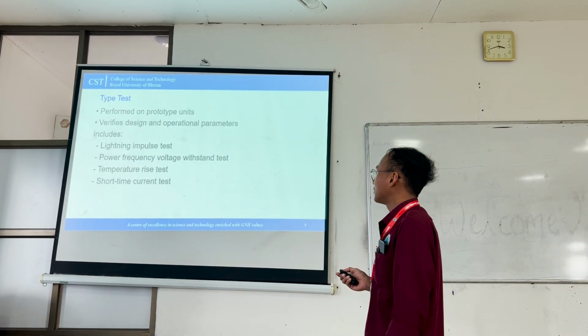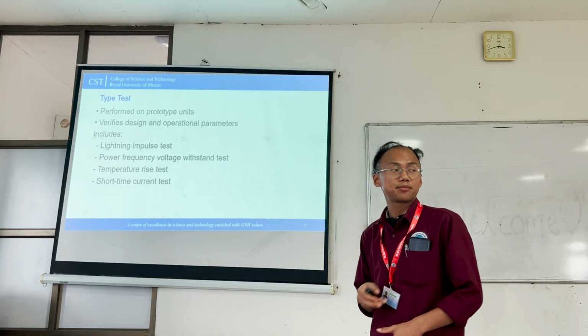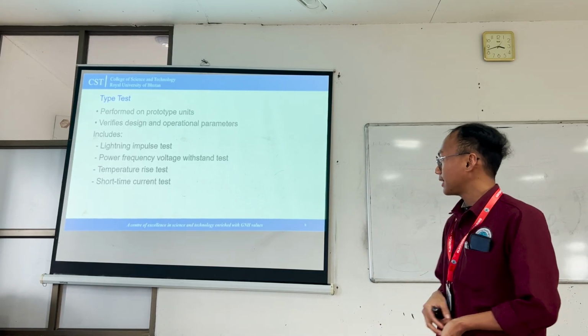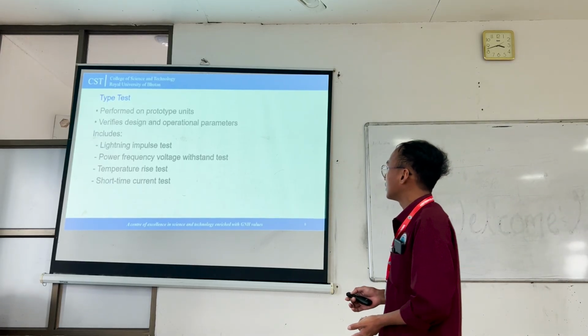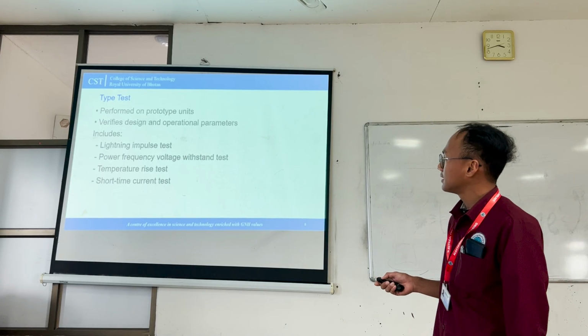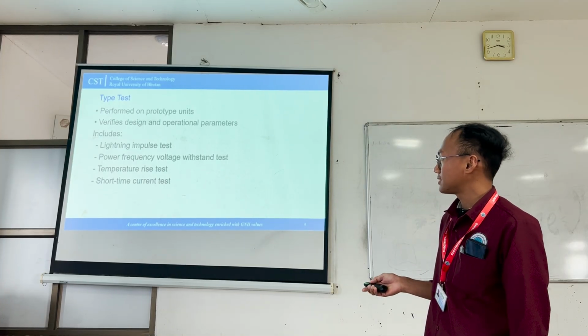Now, moving on to type test. It is usually performed on a prototype isolator and busbar. Now, this includes lightning impulse test, power frequency voltage withstand test, temperature rise test, short time current test.